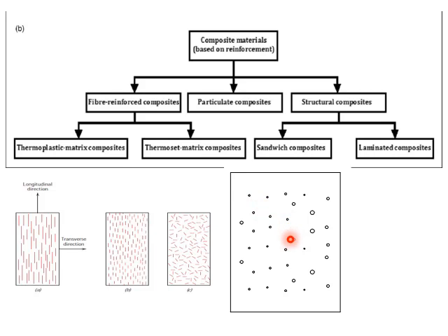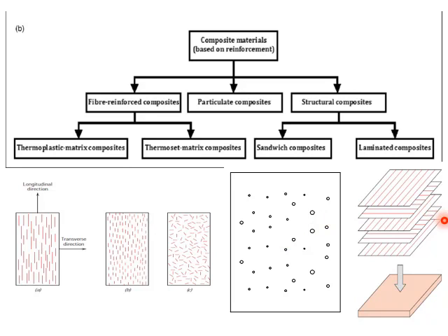And the last one is the sandwich or laminated. If you want strength in all the directions, then you are going to have plies in which the fibers are oriented in opposite directions. You can see in this one it is oriented in a longitudinal direction, in the next one it is oriented in a transverse direction. Like that. How many plies you want depends on the strength of the composite material. Like that you will get one laminate which is made up of many plies which are glued together and compressed in order to give strength to the composite materials.